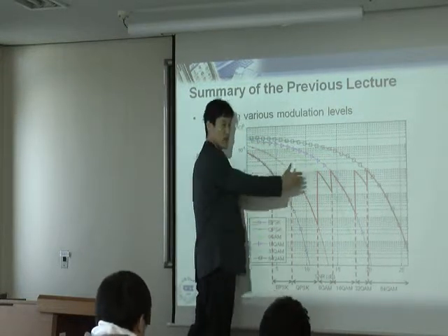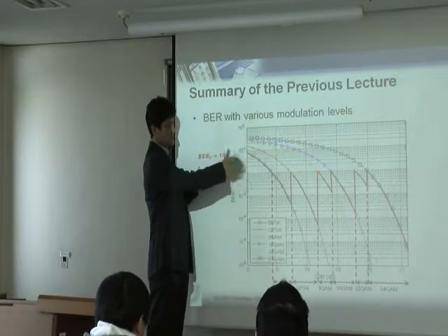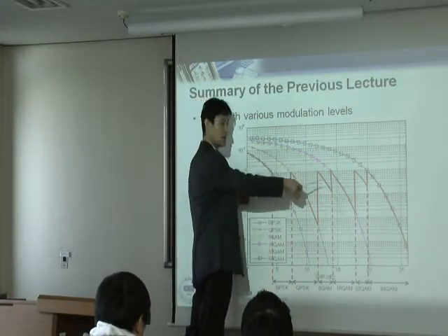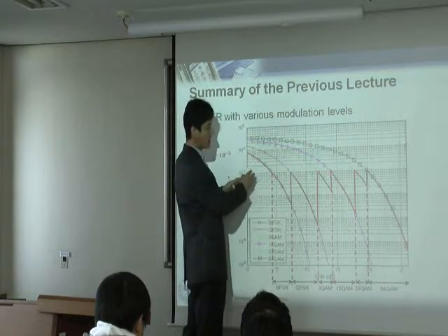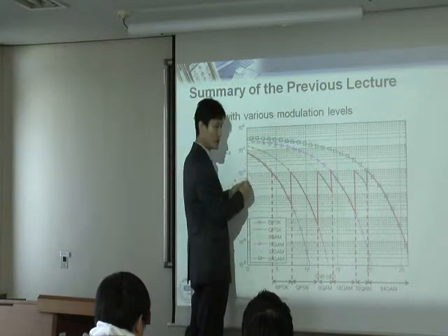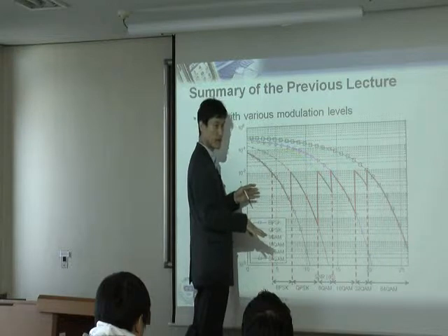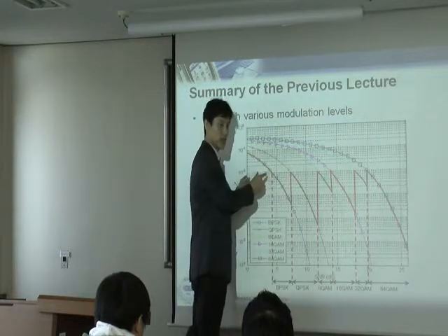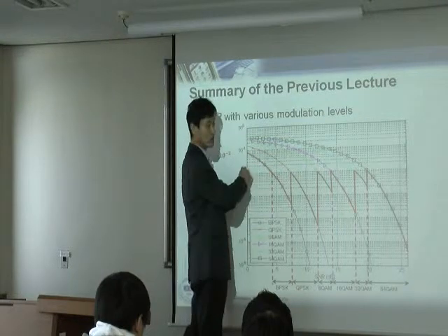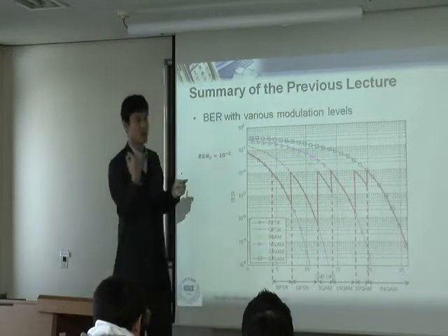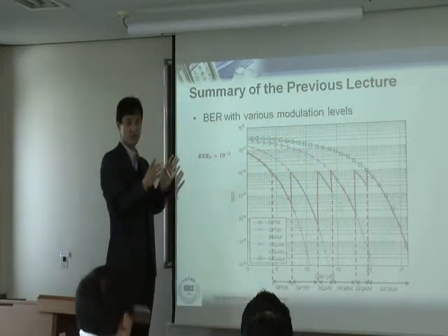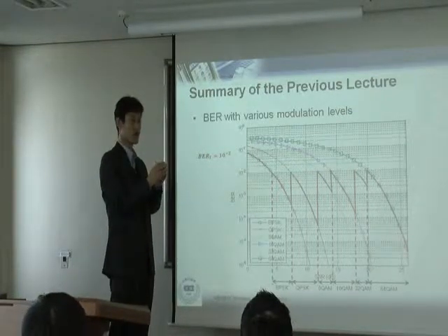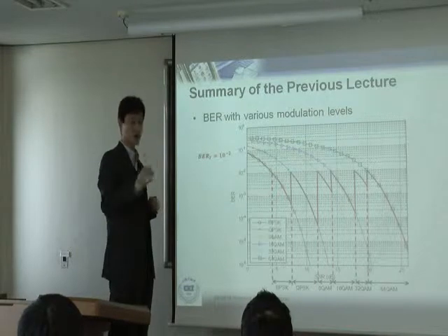So from those studies, once you plot the symbol error rate of all 15 of them, you have to decide which one you want to use and which one you want to drop. Because these 15 combinations are not evenly spaced, you have to select only some number of them, only some distinguishable curves. And those combinations are what you are going to actually use.